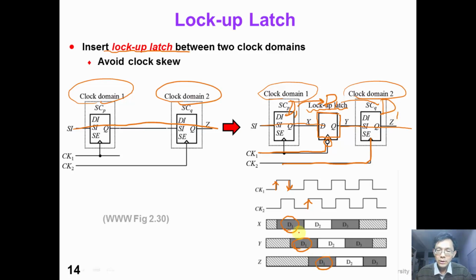As is shown in this timing diagram, with the help of the lockup latch, we can now safely transfer the data from X to Y, then to Z successfully. So we are not afraid of the clock skew problem anymore. So the lockup latch is a very important DFT technique when we insert a scan chain.